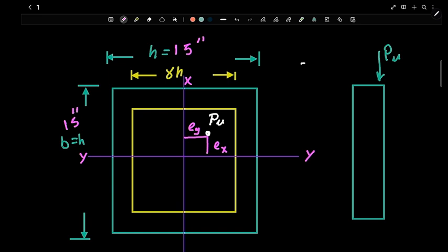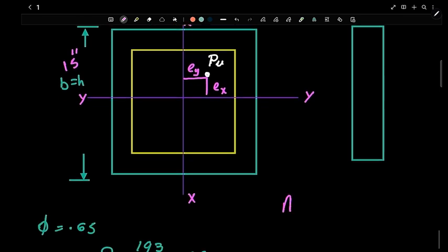And then we're going to use rebar. The rebar AS came out to be AST, area of steel, which came out to be 9.5 inch square. So if I put one right here in this corner, one in the middle right here, one in here, one in there, one in here, 1 2 3 4 5 6 7 8.